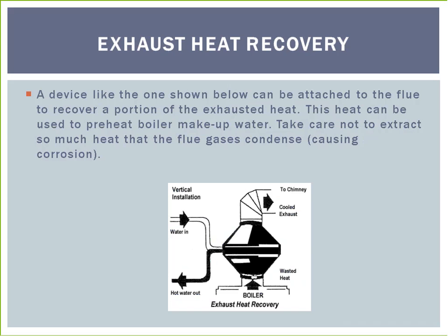A device like the one shown below on the screen can be attached to the flue to recover a portion of the exhausted heat. This heat can be used to preheat boiler makeup water. Take care not to extract so much heat that the flue gases condense, causing corrosion.